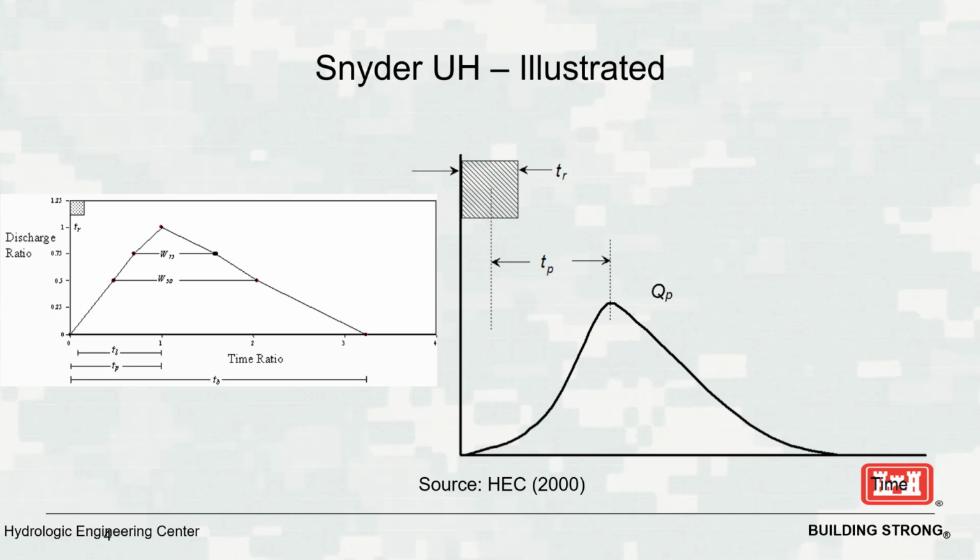The graph shown here shows that there is not a lot of definition to the rising limb or falling limb of your unit hydrograph. In HMS, the Snyder's method only computes the 0, initial base value and the peak value delayed by a lag. The method actually calls the Clark unit hydrograph and iterates through its parameters, time of concentration, and the storage coefficient to create a unit hydrograph that matches the Snyder's hydrograph peak value and peak timing.